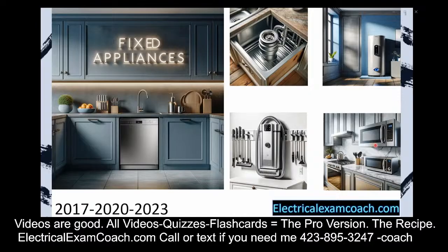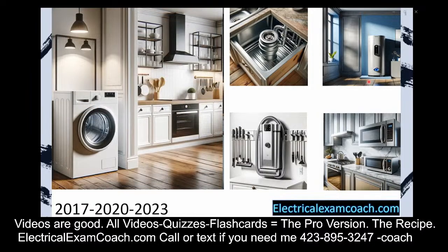And when you fix it to the wall or fix it so it can't move, either with plumbing or mechanical vents or anything else, it now becomes a fixed appliance. And there's a special way that they calculate them when doing a whole home load calculation. What it does not include is dryers or ranges. We're actually going to deal with those separately. So this includes all other fixed appliances except for dryers and ranges.